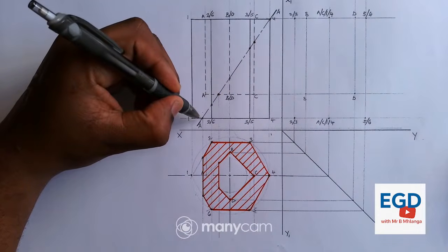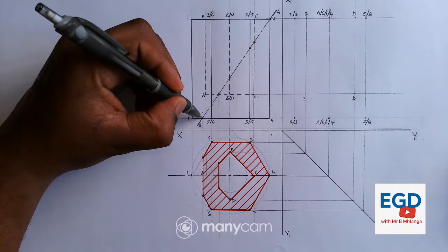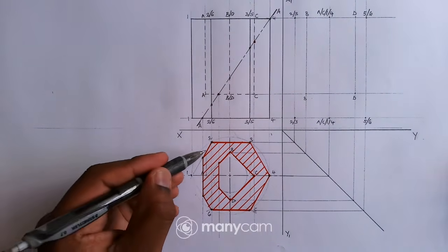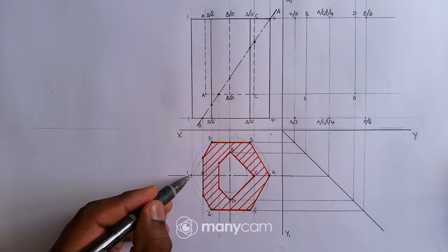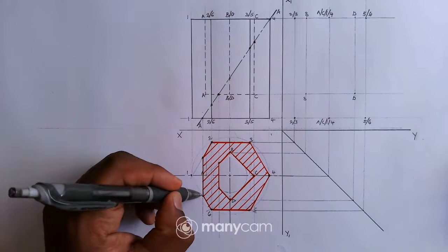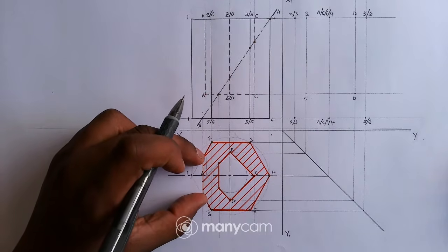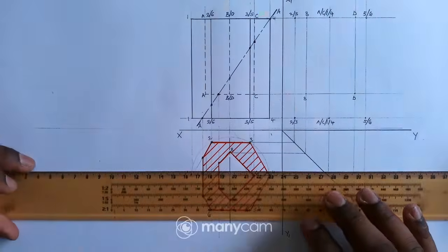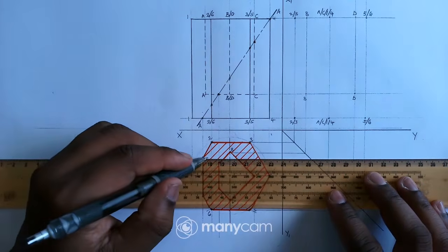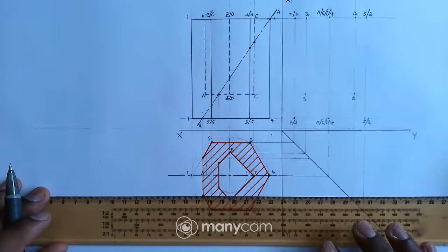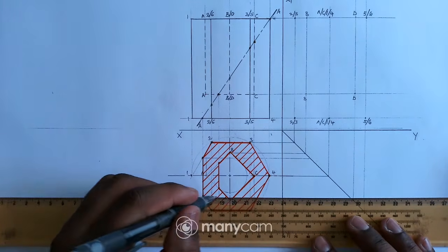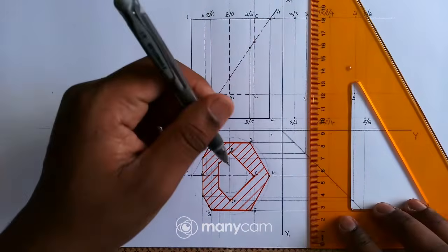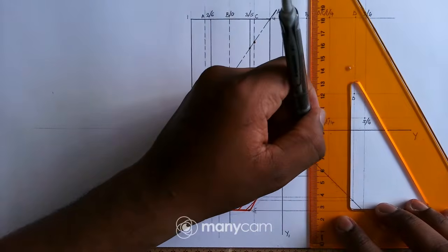The cutting plane here cuts two lines, line 1-2 and 1-6. If you check from our top view, we have line 1-2 and 1-6, and we have 2 points. That means I can just project these 2 points to our sectional left view. So I can project that point first and also project this point as well, and then project them up to line 1-2.